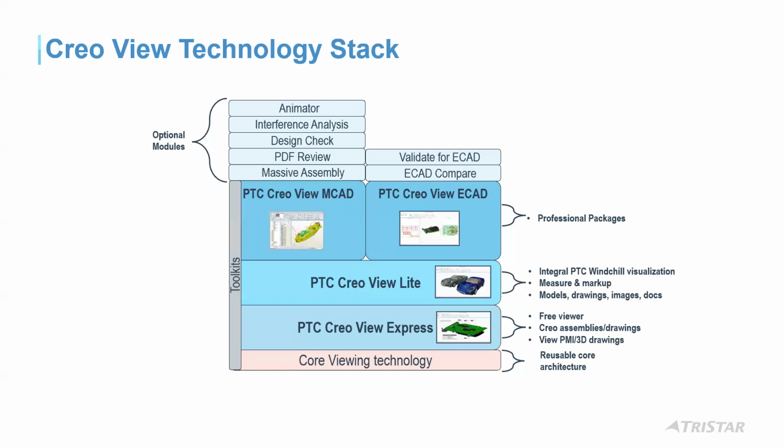Now, sometimes if you have thousands or hundreds of parts in that assembly, you don't want to send the whole assembly. So when you convert it to Creo View format, this allows you to automatically create a zip file that has everything, and you're just sending one file to the person. So you might have an assembly of thousands of components and you just send them one file. Those thousands of components may also include drawings. So if you want to send a drawing with all the parts, again, it's just one file. So it's really convenient.